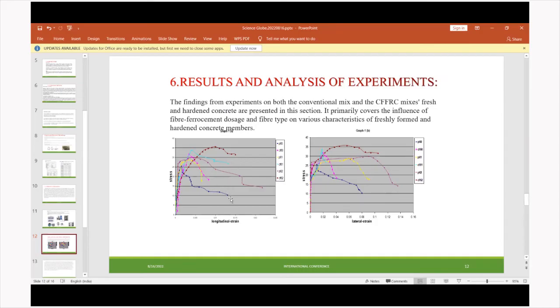In the result, you can easily recognize that if concrete is plain without any mesh and is tested under a compressive testing machine, it will give low compressive strength as compared to the concrete fiber with 6 mm diameter with 2 layers of mesh. Plain concrete with zero mesh is showing low characteristic strength, and the lateral strength, stress and strain are very low. As compared to that, the concrete fiber with 6 mm diameter and 2 layers of mesh has a marginal increase in compressive strength.